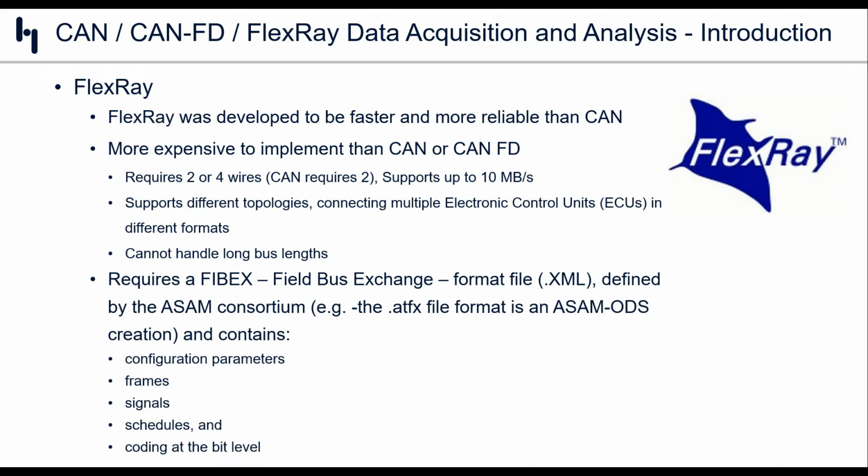So it does require a FIBEX, or Field Bus Exchange, format file. It's an XML format, and it's defined by the ASAM consortium. By the way, ASAM, you might be familiar with that ASAM ODS, is what drives the ATFX file format. So this FIBEX file contains configuration parameters, frames, signals, schedules, and also the coding at the bit level.